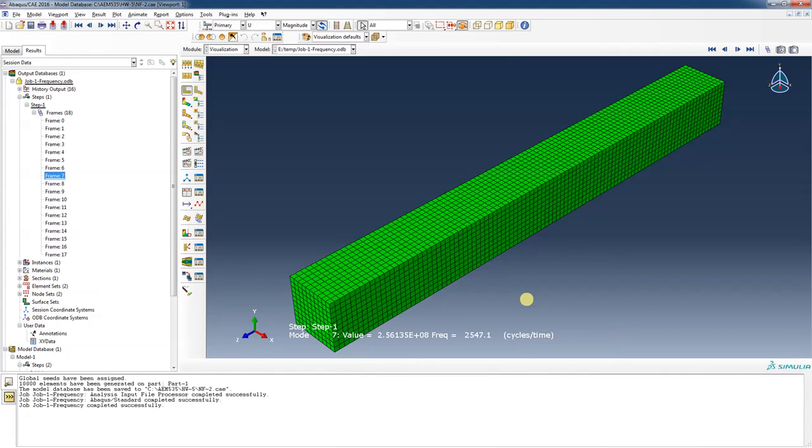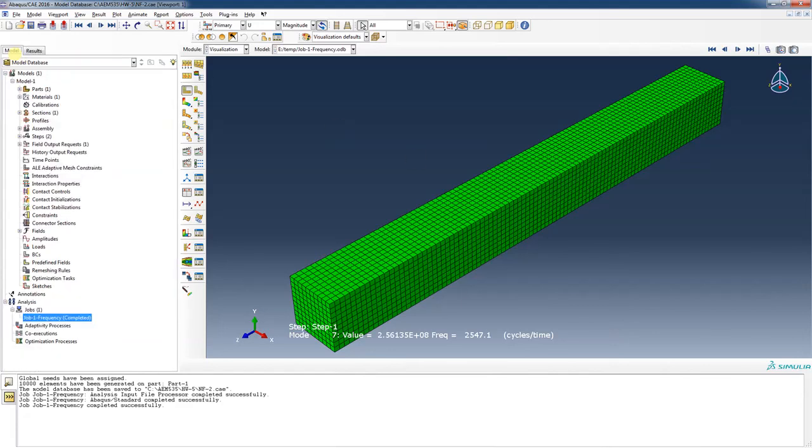But this kind of editing the replay file to create a really quick script is very powerful. So every mouse click, every window move, every rotation, all of that just does it automatically. You have to be a little bit careful about overriding things in your file, but that's a very, very handy feature.